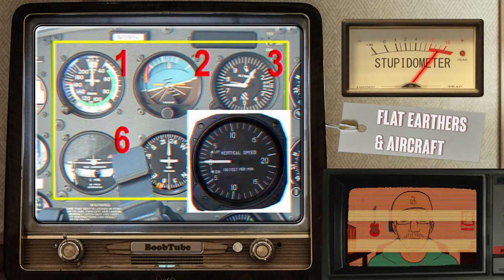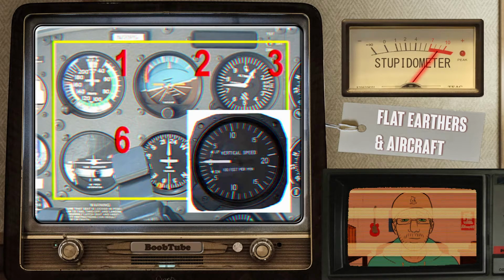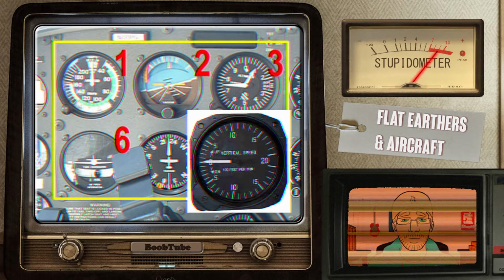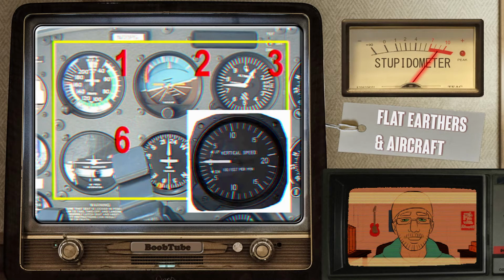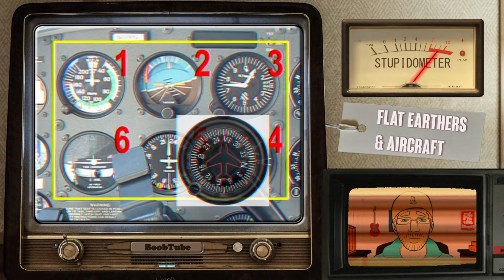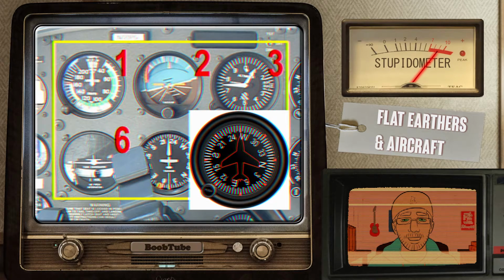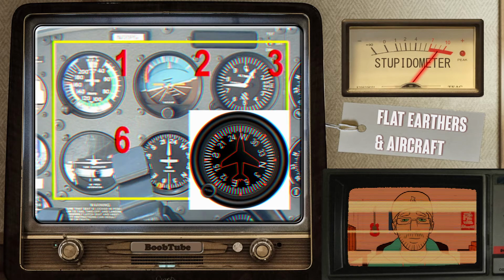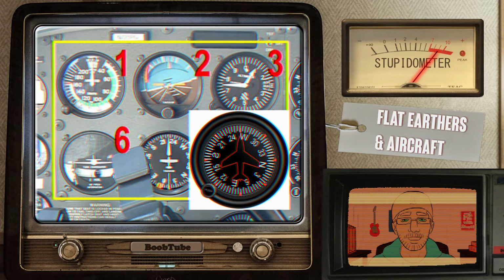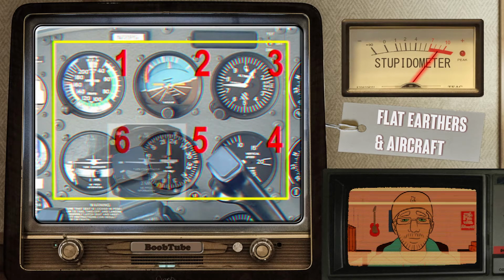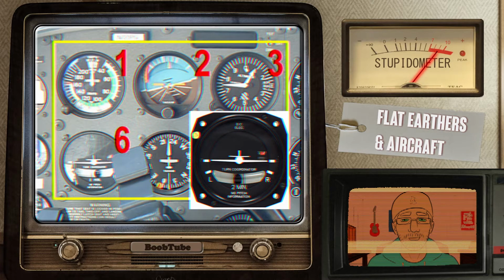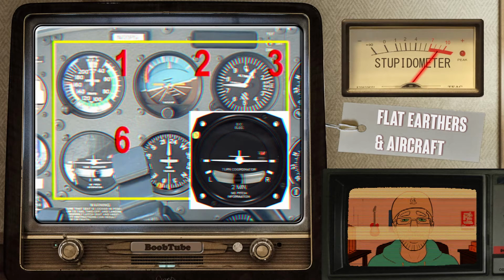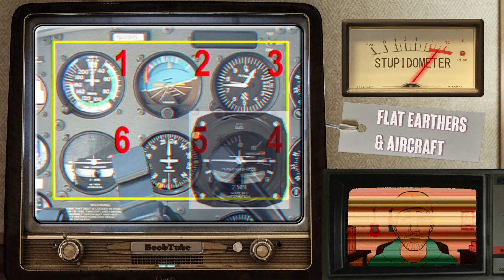This also uses barometric pressure to measure this value. At a glance, the VSI shows if we are flying at steady altitude or if we are ascending or descending. Panel 5 is the heading indicator. This is not a magnetic compass, but instead is based on a gyro and must be set according to the magnetic compass indication before takeoff and occasionally adjusted to the magnetic compass while the aircraft is in steady level flight. Finally, panel 6, the turn coordinator, another gyroscopic instrument giving information on direction and rate of turn.